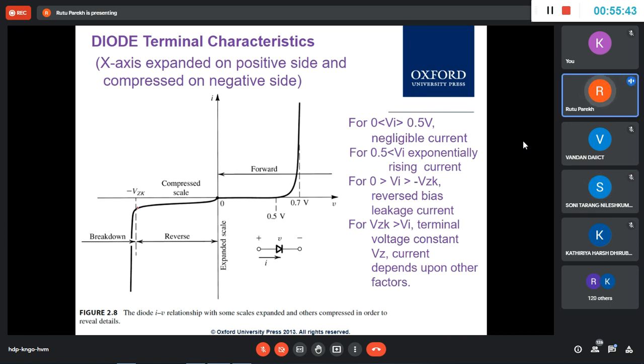For now, this is the Zener breakdown knee current. So Zener knee, that is what we use here. Zener I will teach you at the end of this diode series. So Z is for Zener and K is for knee, like the knee of our leg. The shape is like the knee of our leg. And then this is just to show the different regions. So this is the breakdown region, after which the current flows in the reverse bias direction. So we say this as VZK.